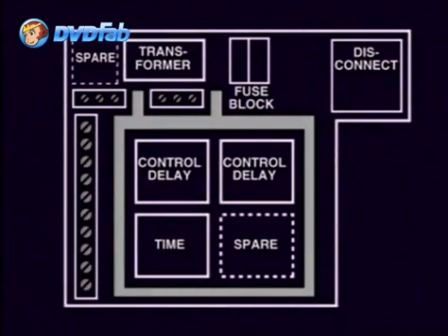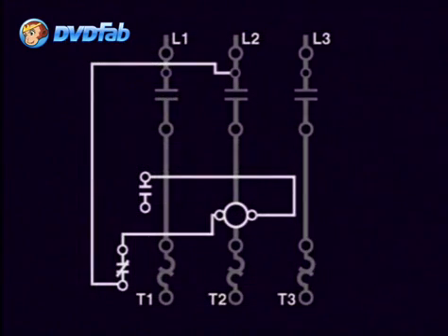A layout and connection diagram gives the physical placement or location of all the components in a control panel, while a wiring diagram, like this one for a magnetic starter, is intended to show you the actual physical relationship of all the various devices that form the control system. Note that the heavy lines are used to represent power circuits, while the thin lines are used for control circuits.